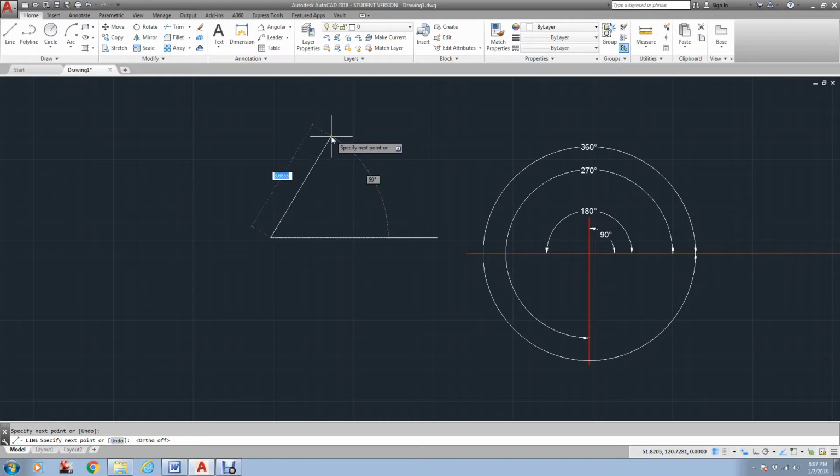So what I'm going to do is type in 5 and then the less than symbol. It is the symbol that shares with the comma. You hit shift. Now as you notice it's looking for an angle, and I'm going to type in 60. So it's created a line. I'm done drawing, so I hit escape just to show you this is the 60 degrees. Now if I would have drawn this line and put in 5 and then the less than and negative 60, it would have come down this way. All your rotation and all your angles go positive to the left.